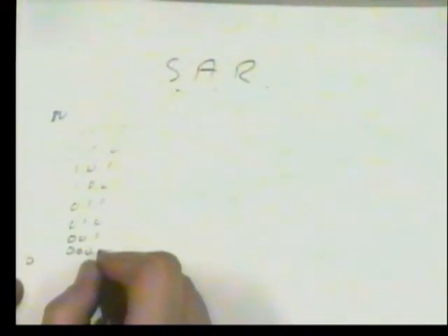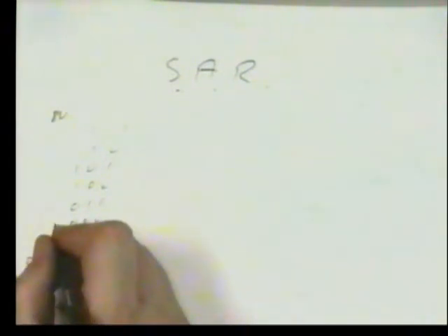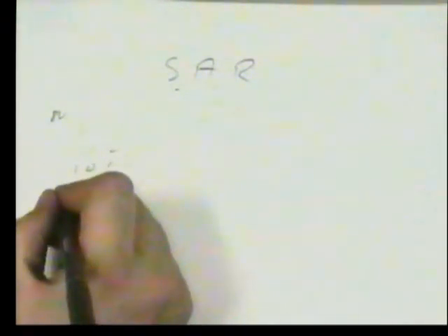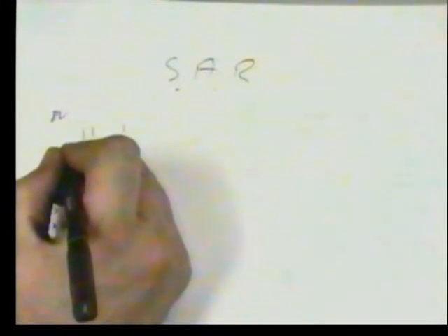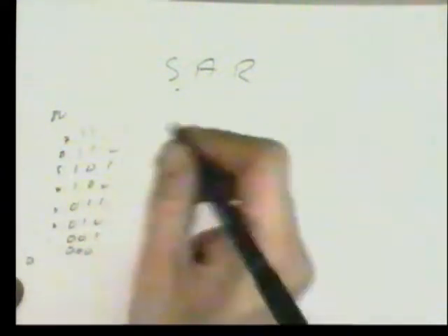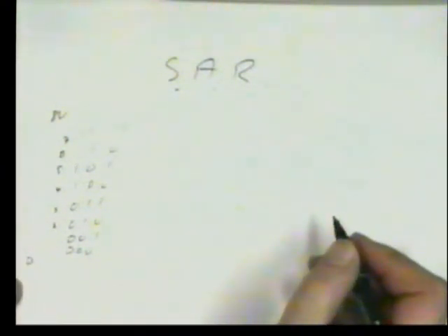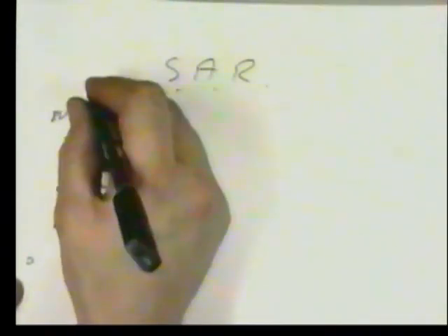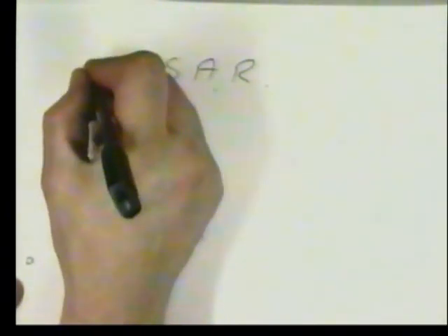And we've got quantization errors. Any value between 0 and 1 is 0 to 1 volt. That's 1 to 2 volts, 2 to 3 volts, 3 to 4 volts, 4 to 5, 5 to 6, 6 to 7, and 7 to 8. So these are our various levels. The most significant bit here means 4 volts.